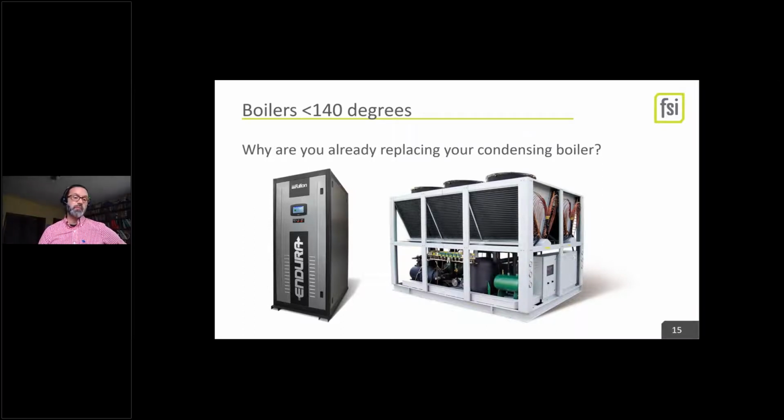But as soon as you do that electric backup, you are really looking at electric capacity of the building, adding electrical service, which again has been a more modest cost than what we thought. We got the warning early on on both projects we've had to do it that it was going to kill the project, it was going to be horrible, and then it ended up being a couple percent of the total construction cost. But still, it's a couple percent, it's nothing to sneeze at, and you've got to know that that is a possibility, that you're going to need to bring in an additional electric service or a larger electric service.